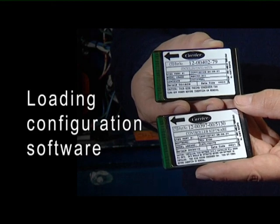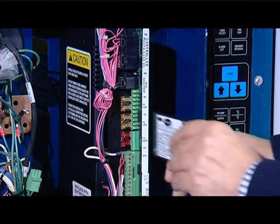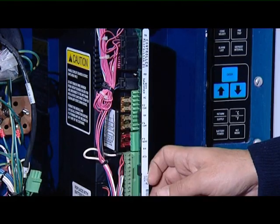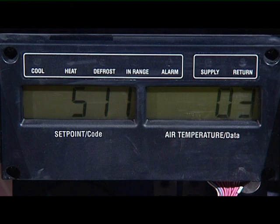Procedure for loading configuration software. Switch off the unit and insert card. Very important. The white label from the card should always face the condenser fan. Switch on the unit. The display will show the unit model series in the left window, for example 511, and in the right window will indicate the dash number for a given unit model.